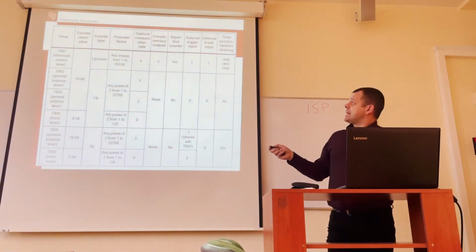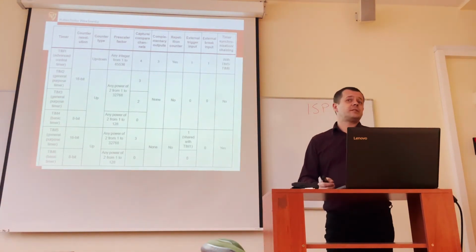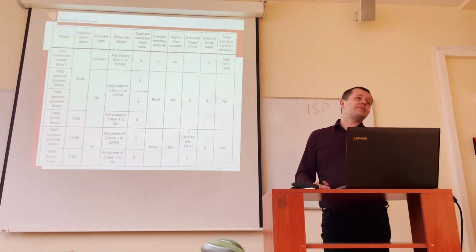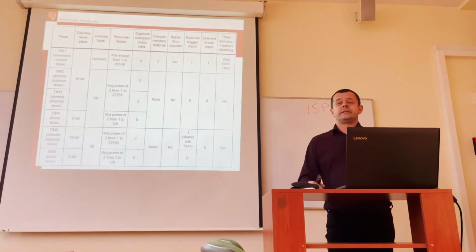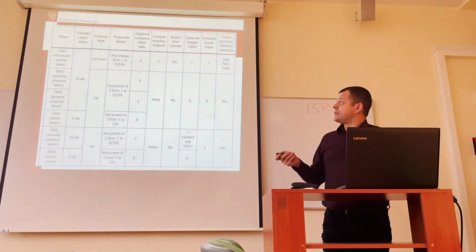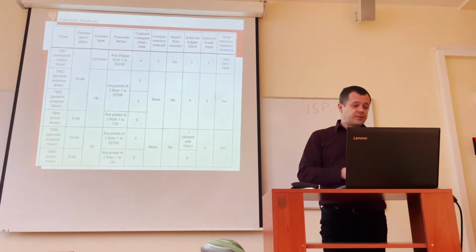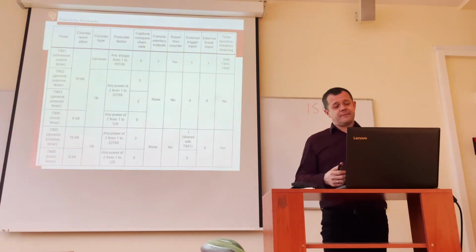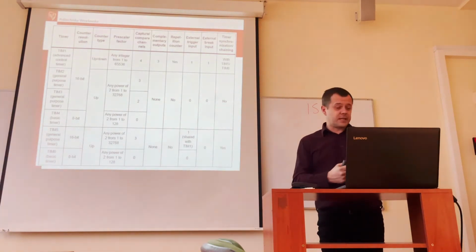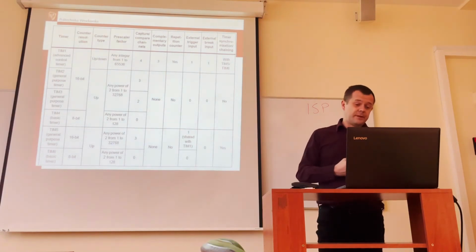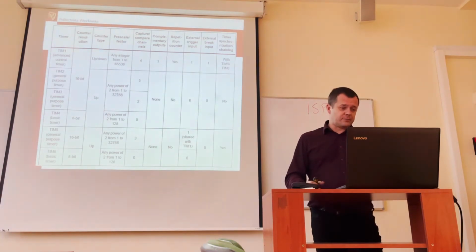Then another feature of the counters is whether they can count bidirectionally or just in one direction. Again, a very simple functionality. In larger microcontrollers, the timers are by default up-down. Here in this small microcontroller, that's what you can be afraid of in case of microcontrollers with 8-bit CPUs. We may have such queer options like just up-counting timers, but still, here it is. Just one timer is able to count up and down. The other ones are just up counters.